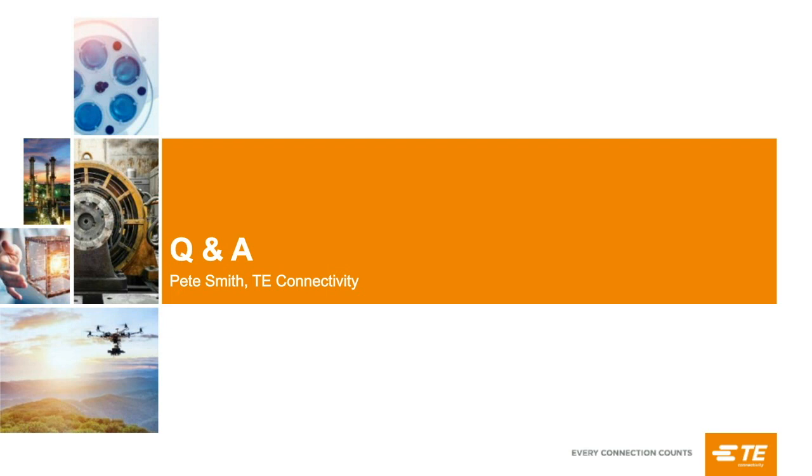And if necessary, we can manufacture custom products that can go to much higher pressures. We do a pressure sensor, for example, for the fuel injection rail on automobiles. I think that the pressure range is 30,000 psi. And those are available. Those in automobile applications, it's not an I2C interface. It's a CAN bus type interface, obviously, because it's automotive. But I2C interfaces are easy to do. So yes, the answer is yes. We can provide an I2C digital interface with very high pressure gas sensors.